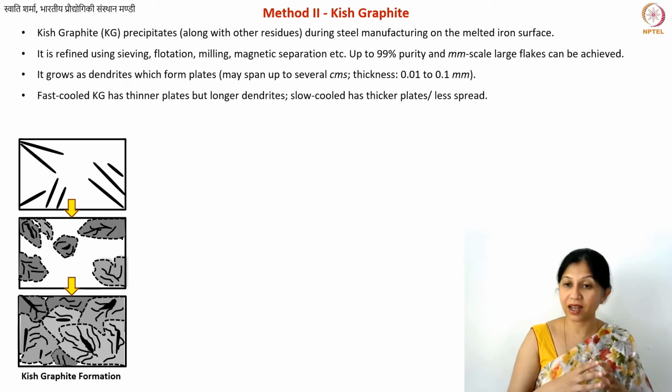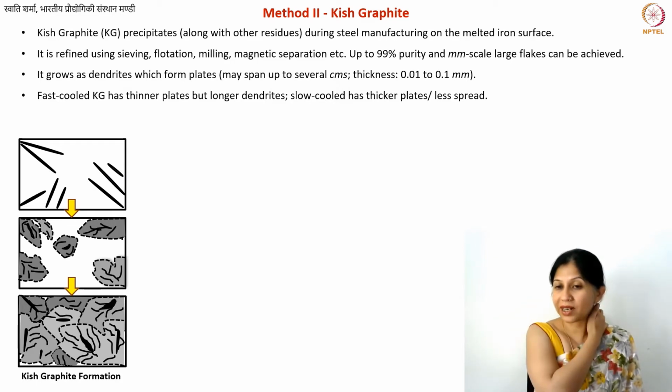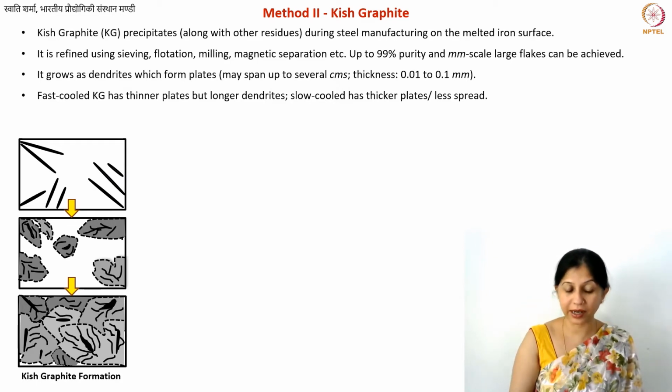So you can have either long but thin flakes, or short but thick ones. You want thick flakes when you want a larger Lc. What is Lc? Lc is the stack thickness. If that is more important for your application, you would choose the conditions accordingly.